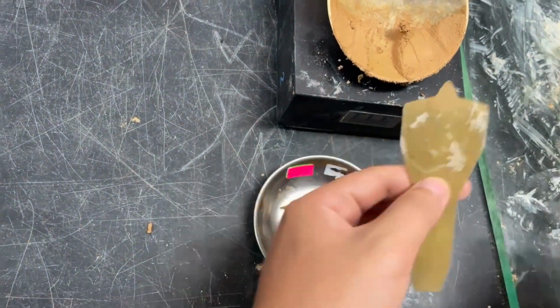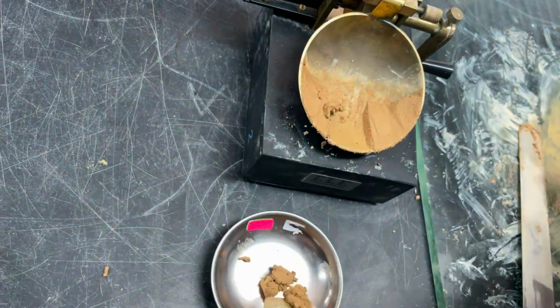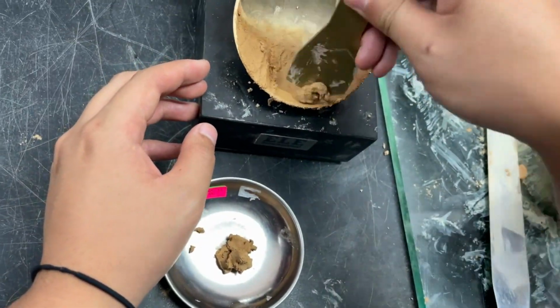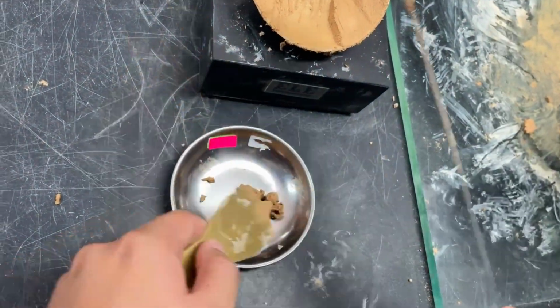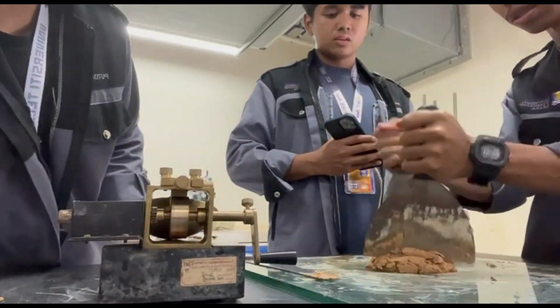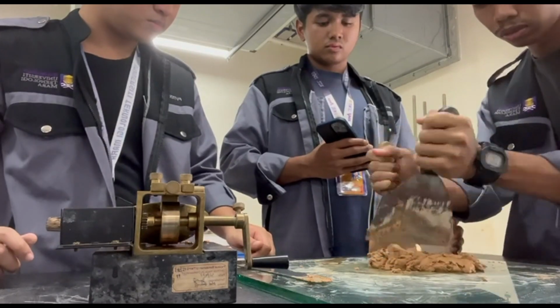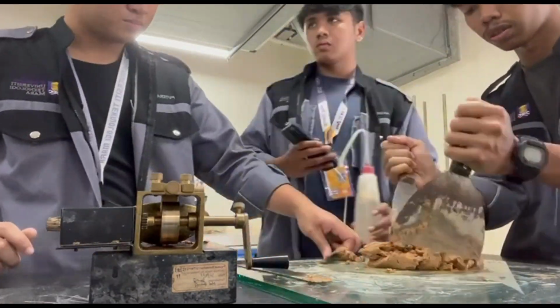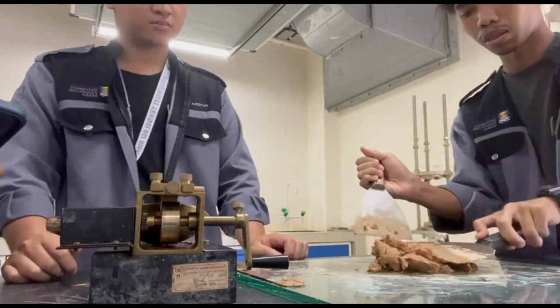A sample was then taken, including the soil on both sides of where the groove came in contact. The soil was placed into a moisture can and was immediately weighed. After that, the entire soil specimen was remixed on the glass plate with a small addition of distilled water to increase the water content so that the number of drops required to close the groove decreased.